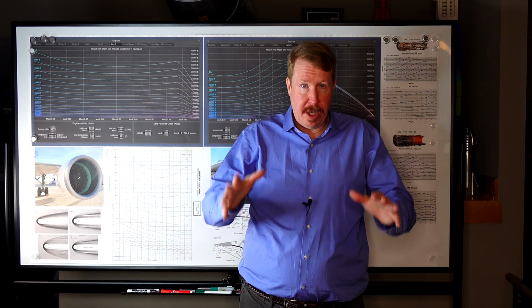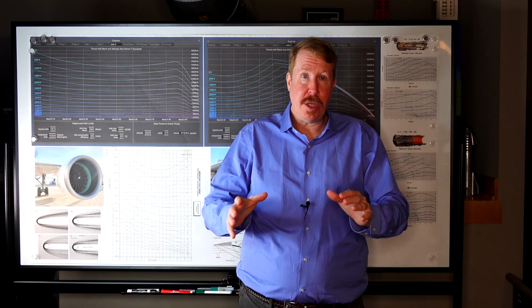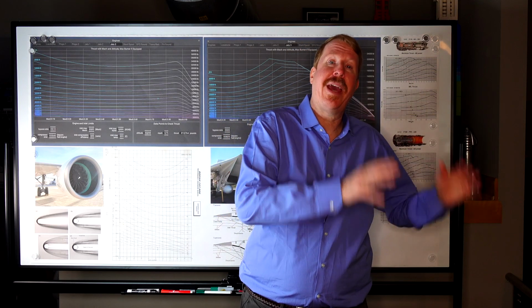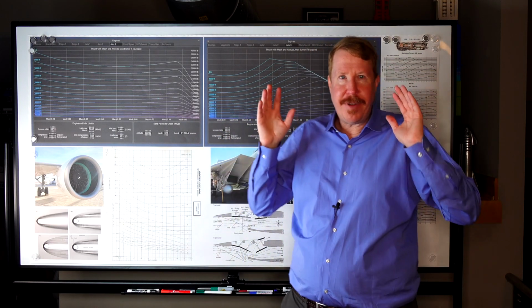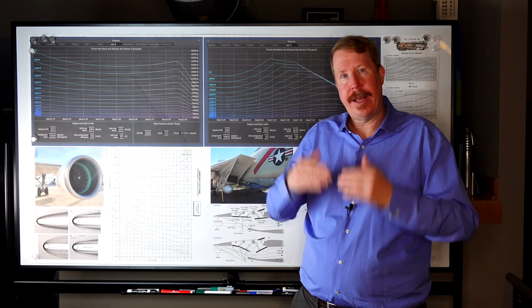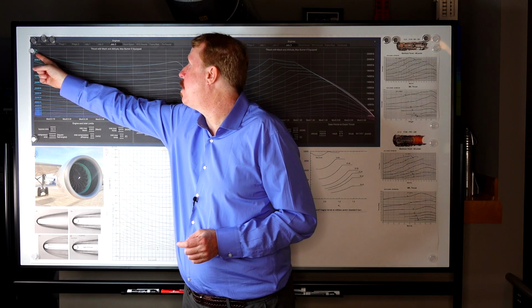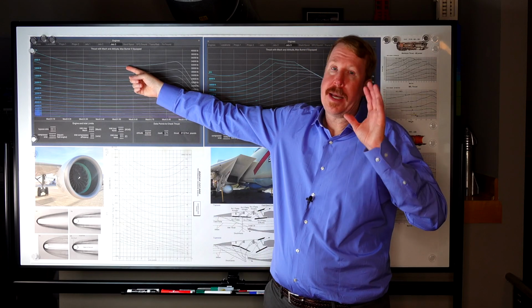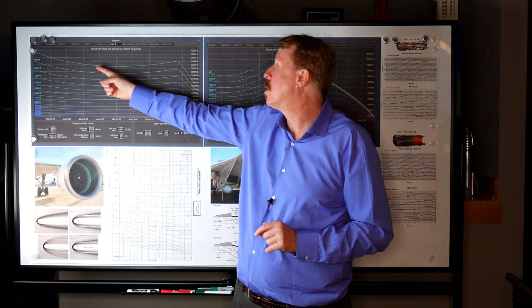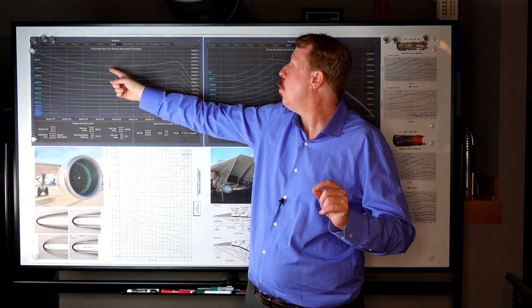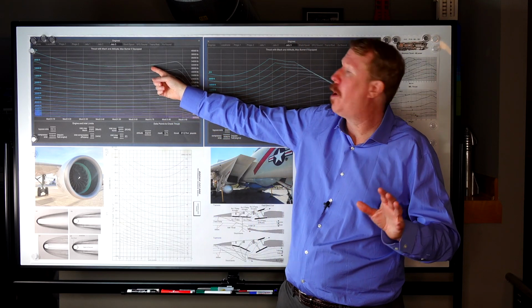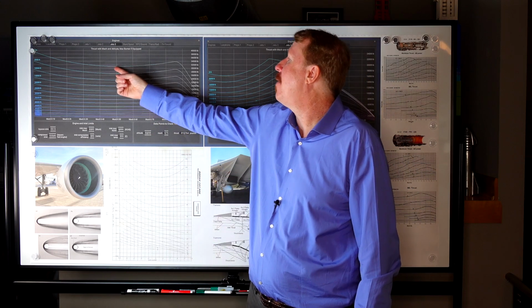Remember, if you have a limited amount of power available, then the faster you go, the less hard you can push. That is the definition of fixed power. It's less thrust the faster you go. And so we see that here. Less thrust the faster you go is that compressor puts out a constant unchanging horsepower. However, once you get above about Mach 0.5 or Mach 0.6, a ram air effect comes in and that starts kicking your thrust up.